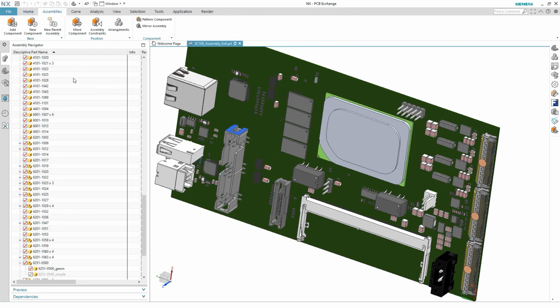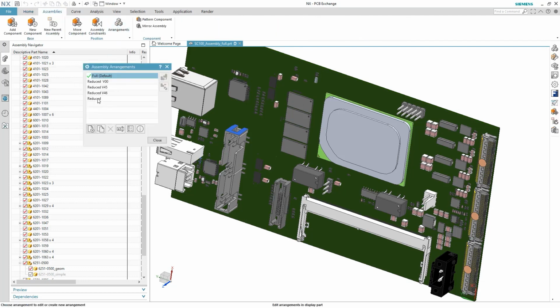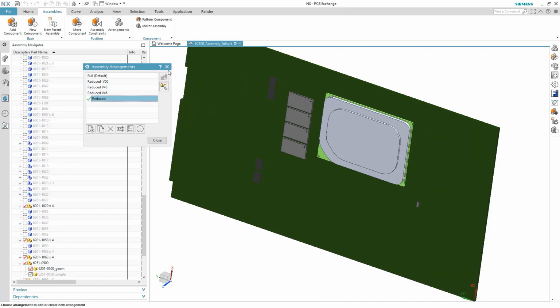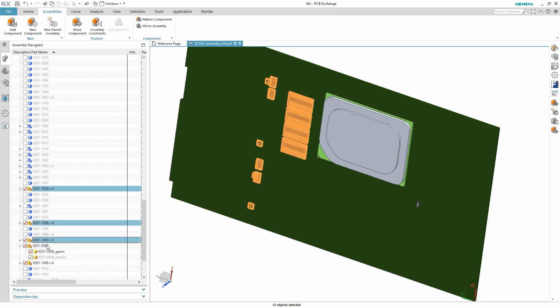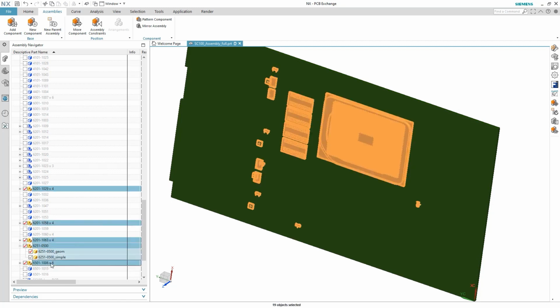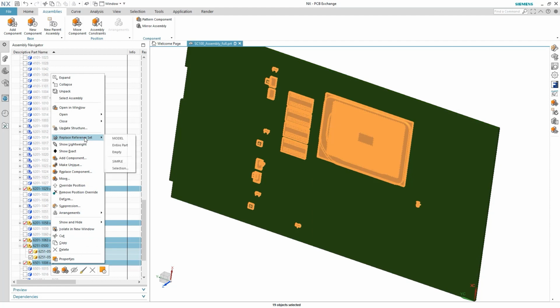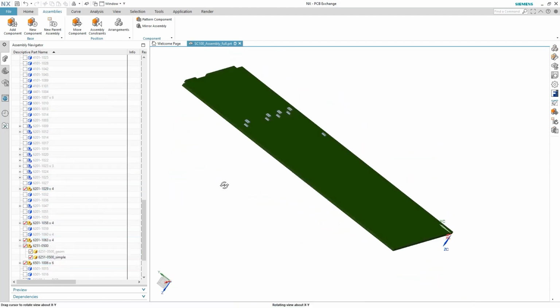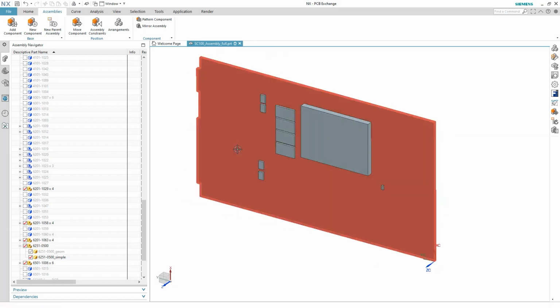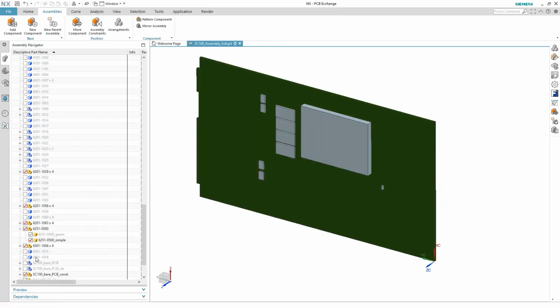First, let's do an arrangement of the assembly. To simplify the geometry for the FLOEFD solver, I'm using basic thermal models for some electronic components and exclude some other components from the analysis. These models can be built from the data available in the manufacturer datasheets. This decreases calculation time significantly while still giving accurate results.